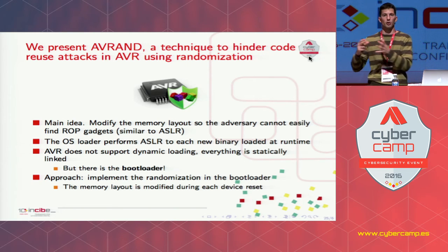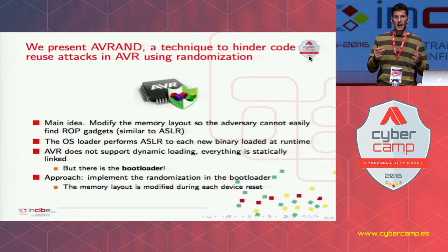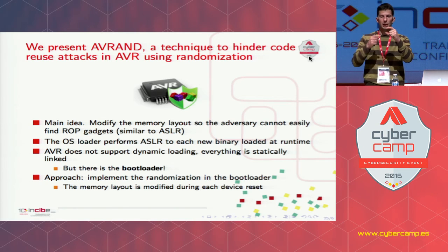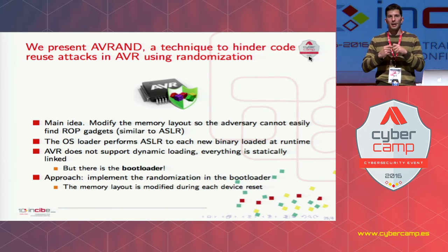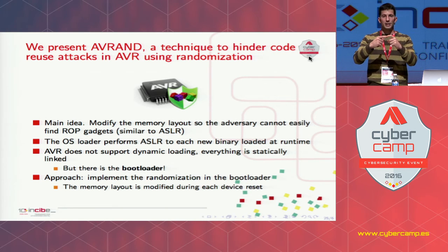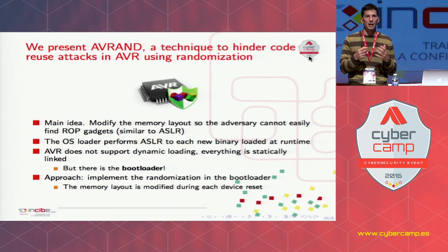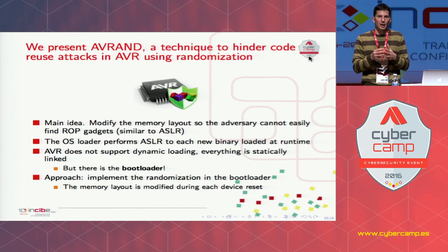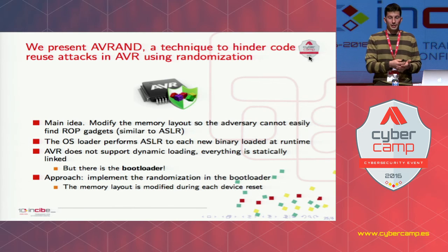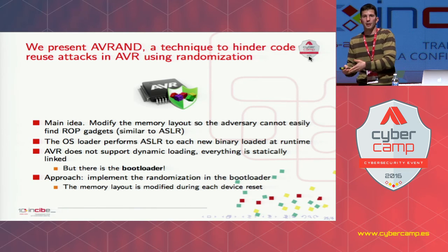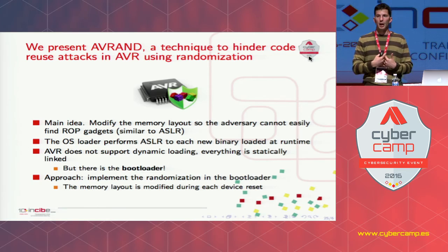And we don't have an operating system uploading modules when the user clicks there. So the first thing to run is the bootloader, which is for boot time. The randomizing machinery and logic are implemented in the 4 KB available for the bootloader. It was complex, and we used the rand function in C. We cannot use a Mersenne Twister. It would be too complex and it doesn't fit in. It was lightweight, but it works.